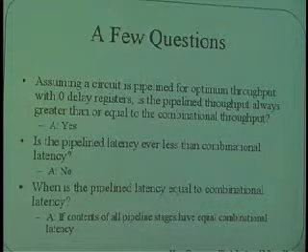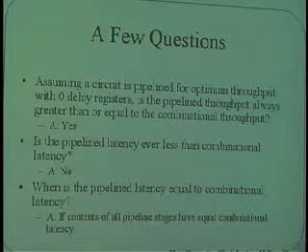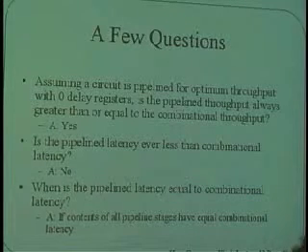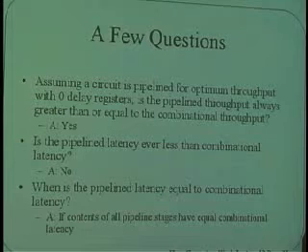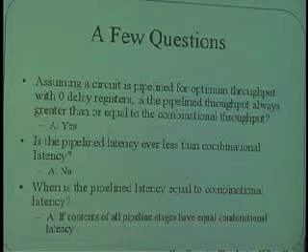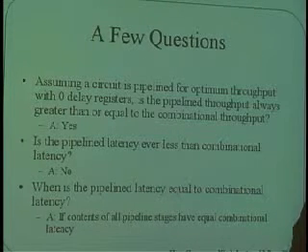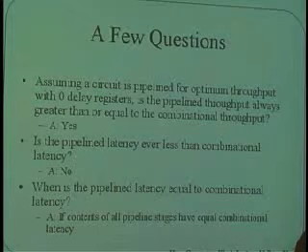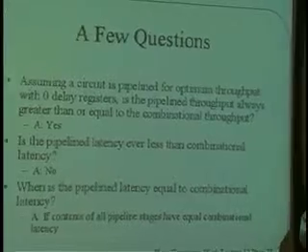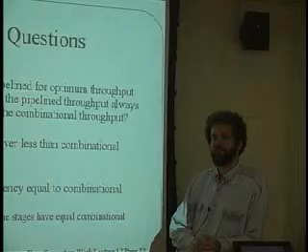Why is the pipeline throughput always greater than or equal to the combinational throughput? And combinational means it's just the logic with no registers at all. Because if the registers have 0 delay, then we're never changing what any particular piece of data is doing. That sort of sounds like a latency argument. Well, this is a throughput question. Right, but we're never making it harder for data to get in at the top. I don't buy your answer. Sorry. We're never leaving something.